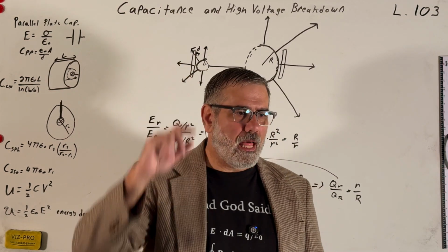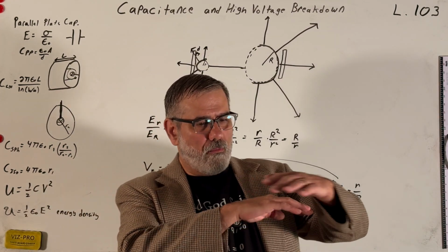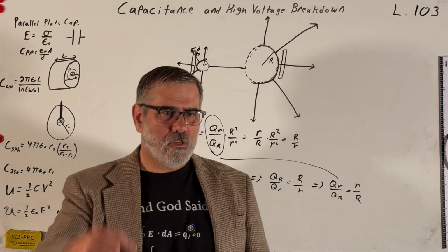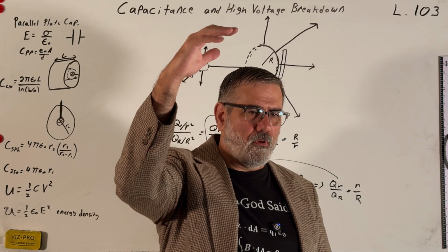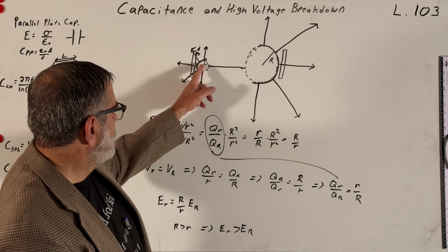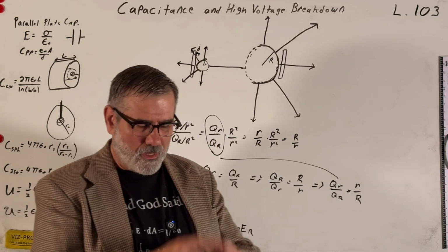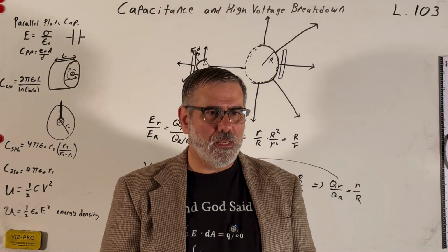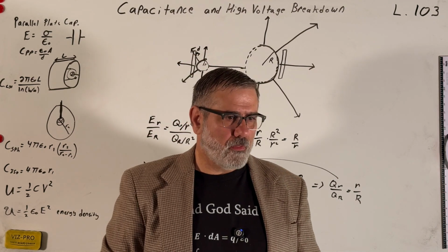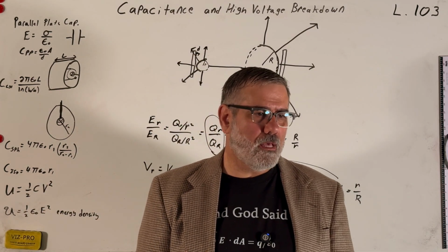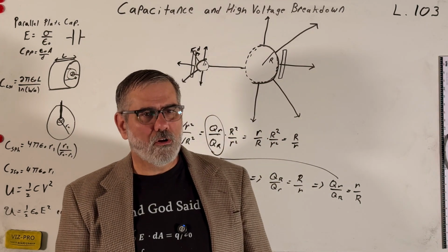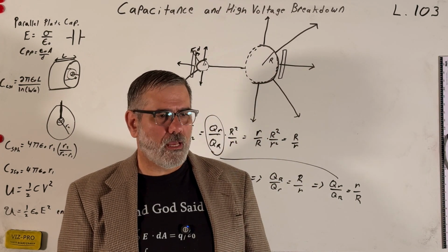What happens is up in the clouds, as different air rubs over itself, right, you get these charge buildups, and you get a large discharge, so you get a very large number of negative charges up in the sky. This is going to cause positive charges to accumulate around the tip of your lightning rod, and eventually the voltage difference between the two will become great enough that you'll get the dielectric breakdown and lightning will form, basically. That's an overly simplified version of it, but that's generally the idea. Okay, so the sharp points can afford much larger electric fields and will therefore facilitate dielectric breakdown.